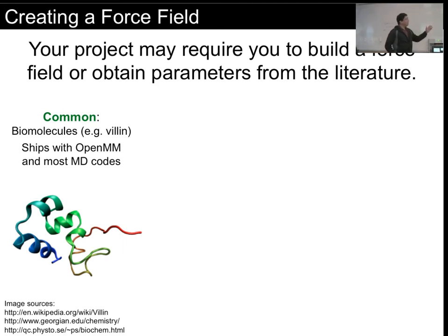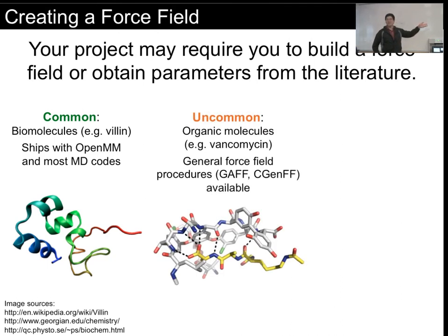So these force fields, you might recognize some of them by the names Amber or CHARMM, and they ship with OpenMM and most MD codes. So if the system that you're simulating is entirely encompassed by proteins and water, well, your main challenge is choosing which force field is most appropriate, right? Like there's going to be 50 of these or hundreds, and you just have to browse through the literature and see which one is best for your application.